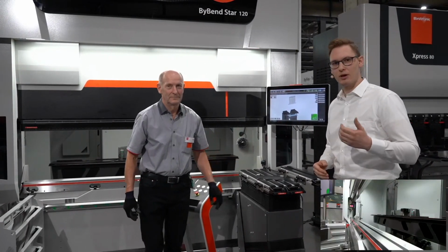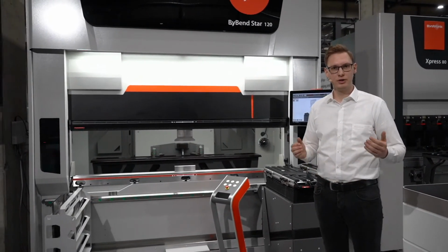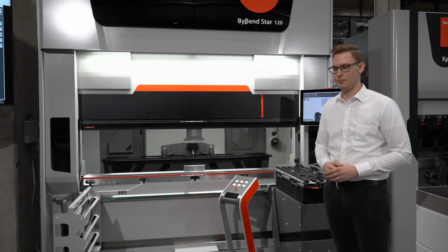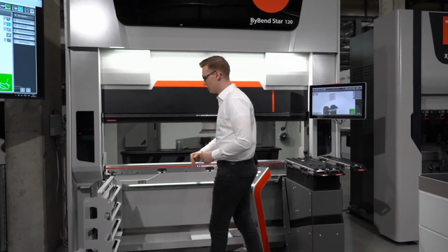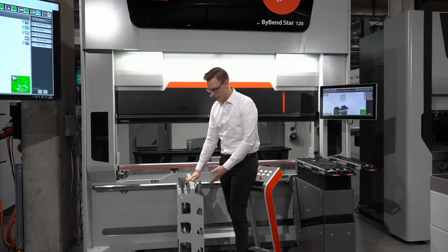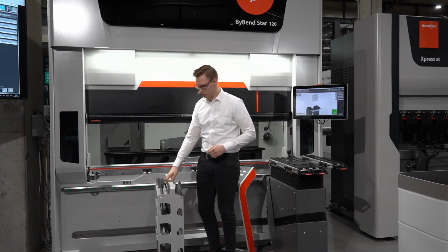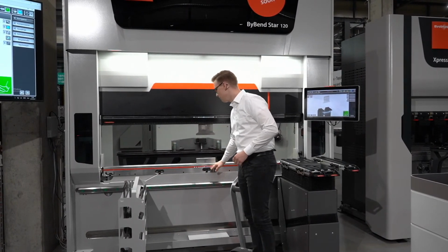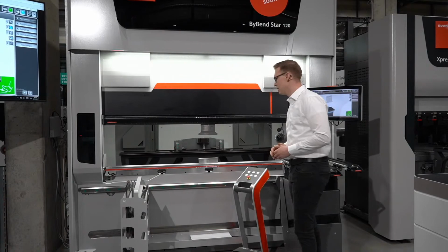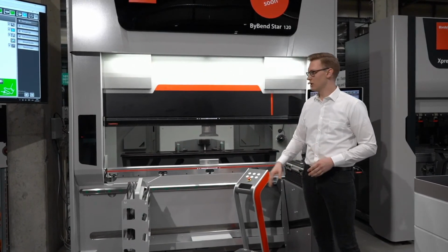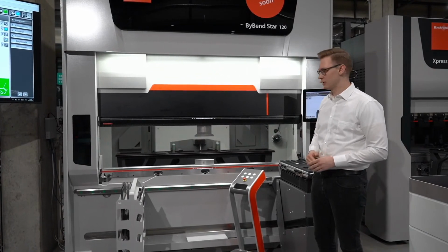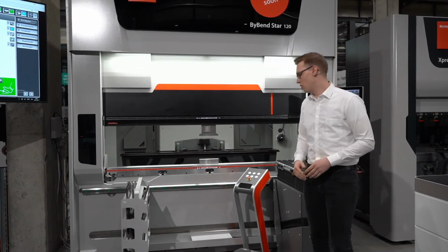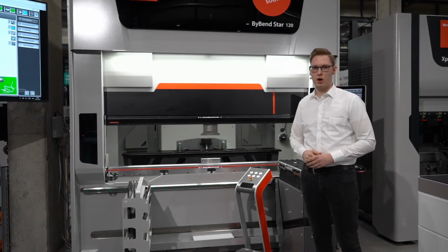And besides speed, quality is always a big issue today. So this machine will also be available with a laser angle measuring system. And we have created other great features. For example, a tool shelf directly at the machine. You can store up to 5 meters of tools directly in front. We have an optical bend guiding system in the upper and lower beam, and we have a motorized safety system, so you do not have to adapt your safety system manually. And if you bend bigger parts, then we have some bending aids to support our and your operator in the best way.